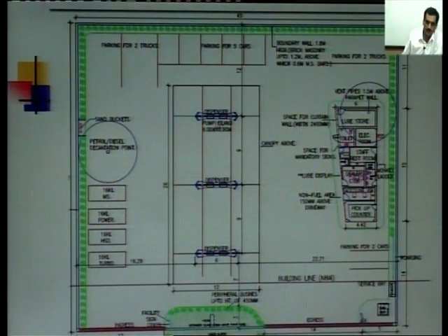So apart from this driveway, then you have islands, then we have underground storage tanks. So underground storage tanks, these are located under the driveway. There are two options of housing underground fuel storage tanks. Number one, it's in BM pit, what you call brick masonry pit, or the other way around, it's in an earth pit.